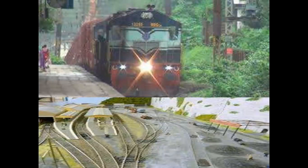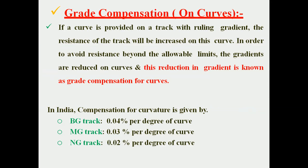Then grade compensation. What is grade compensation? In curves, if a curve is provided on a track with ruling gradient, the resistance of track will be increased. Obviously, in order to avoid resistance beyond the allowable limits, the gradient normally provided on this curve is reduced.